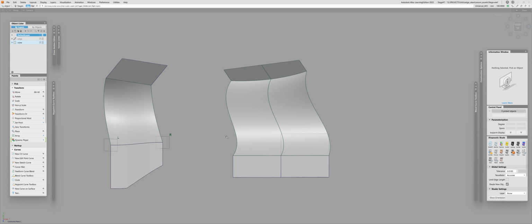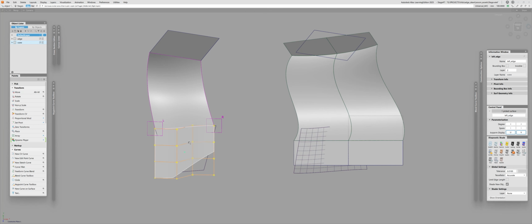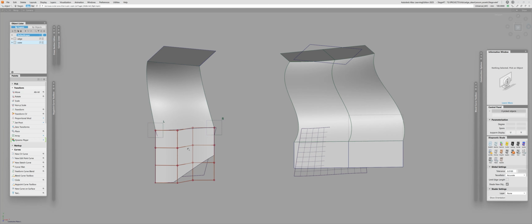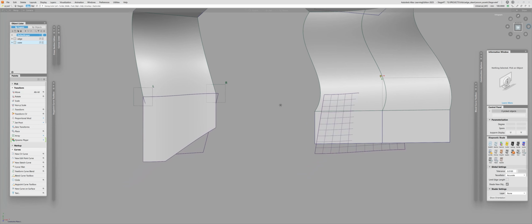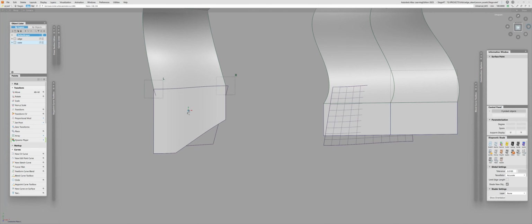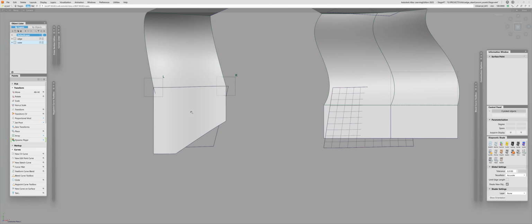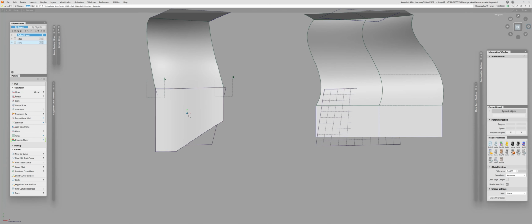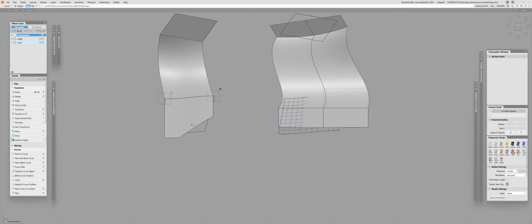Alternatively, you can maintain the same parameterization of the surface before you perform the trimming operation. Let me just quickly show you that again. So you align not to the original surface. Oh, sorry, let me just trim that like this. So you align to this yellow boundary, right? And even though you sacrifice your edges because they're not following anymore, the body will work as intended.